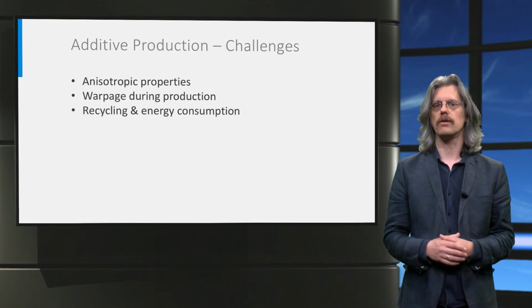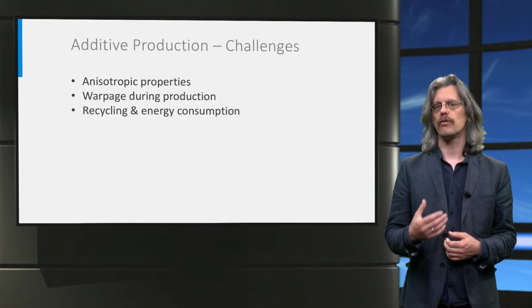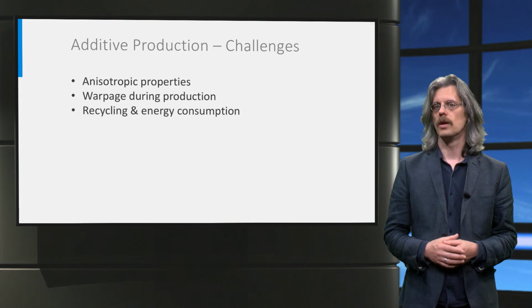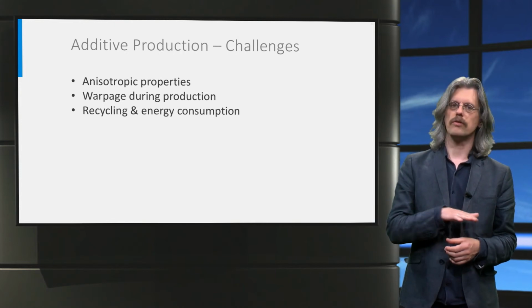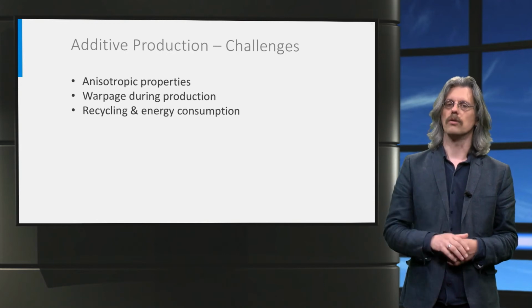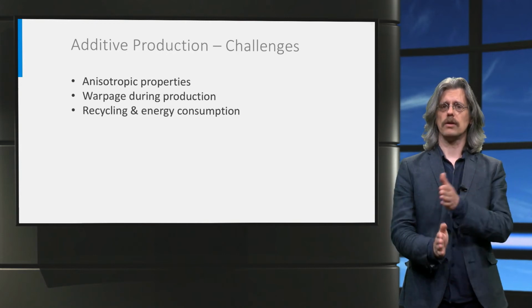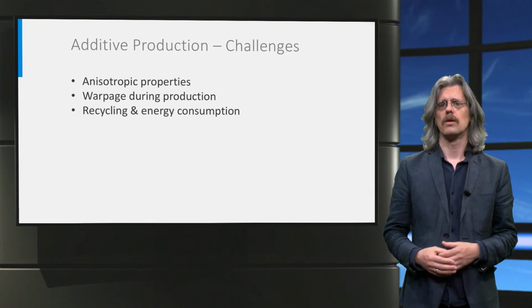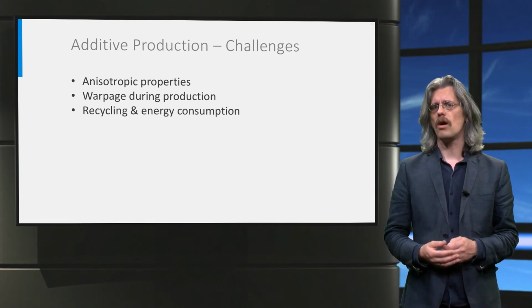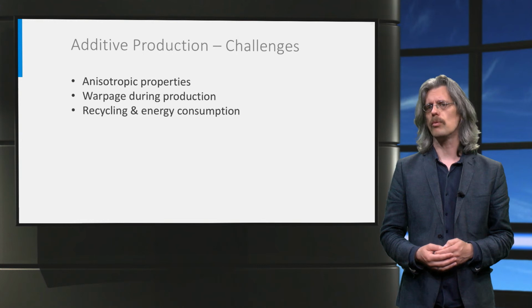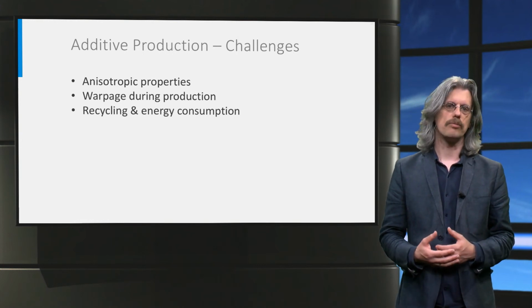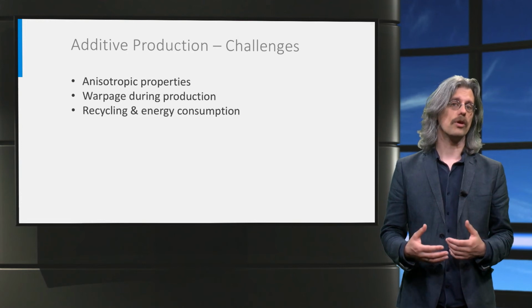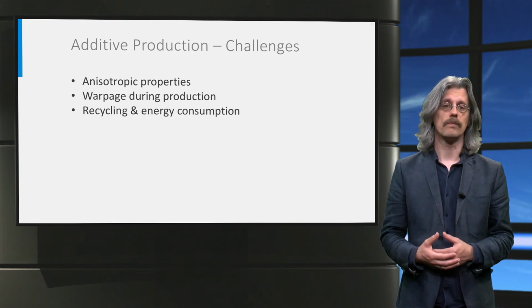Common challenges of additive manufacturing techniques are first of all anisotropy. By the layered manufacturing, the strength of the objects is different in different directions, and often the horizontal plane is better than the vertical direction. Furthermore, this often also influences the visual and tangible properties of the printed objects. Careful planning of the printing direction, also known as the build-up orientation, is required.